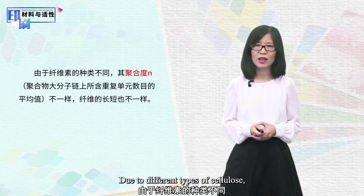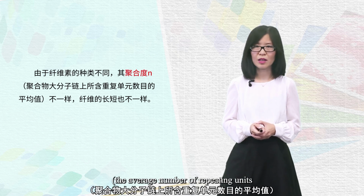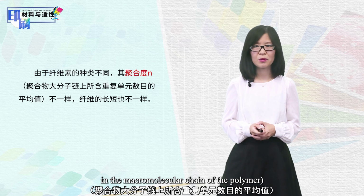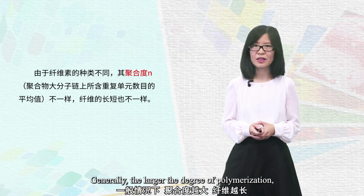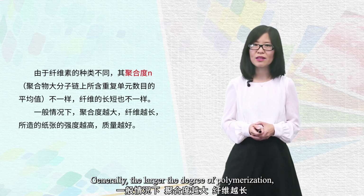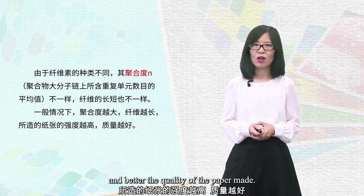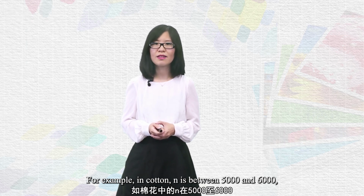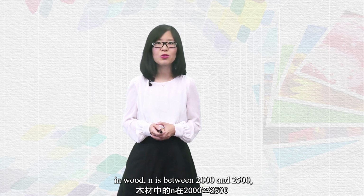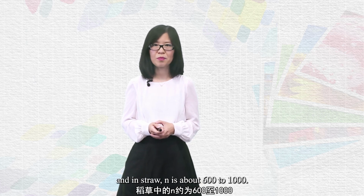Due to different types of cellulose, the degree of polymerization n, the average number of repeating units in the macromolecular chain of the polymer, varies, and the length of the fibers also varies. Generally, the larger the degree of polymerization, the longer the fiber, and the higher the strength and better the quality of the paper made. For example, in cotton, n is between 5,000 and 6,000, in wood, n is between 2,000 and 2,500. In reed, n is about 1,000, and in straw, n is about 600 to 1,000.